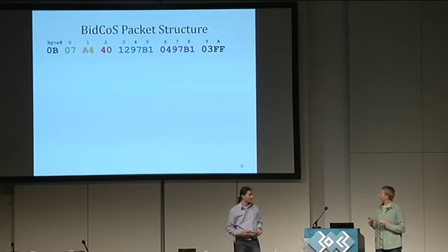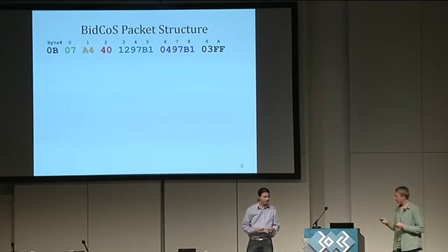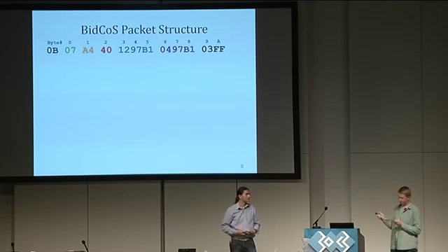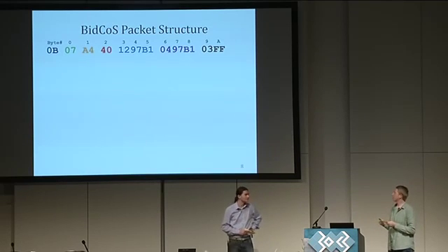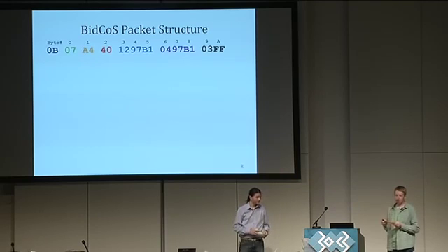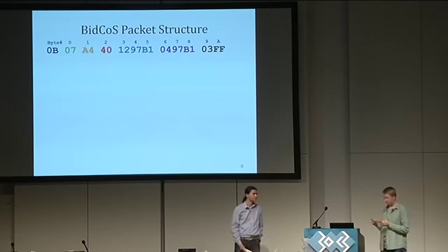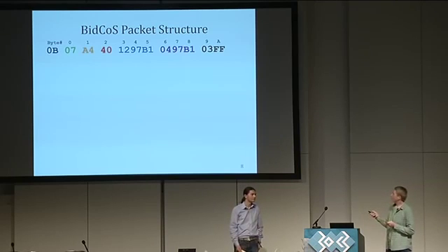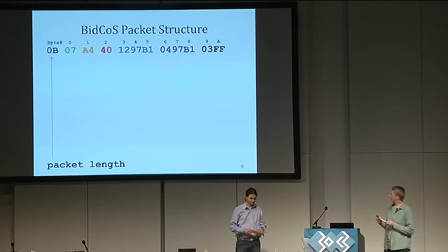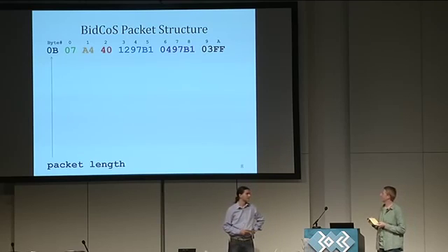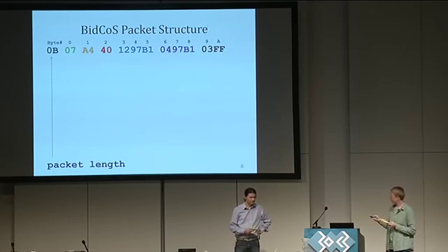Okay, the wireless packets. The protocol used by the HomeMatic devices is called BidCoS, which stands for Bidirectional Communication Standard, and works on a frequency of 868 megahertz, as a lot of wireless home automation systems. And all the BidCoS packets look like this. First, you see the packet length, which does not include itself. So the length counts only the bytes after the length.